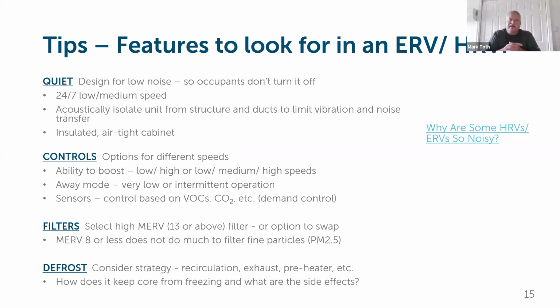On the ERVs, generally, ERVs don't have a defrost cycle that has water, but some do. So it's not a blanket statement. There are some ERVs that need a drain also. The ones that I'm most familiar with do not have a drain. The company I work with mostly has no drain. Units can go in any position at all. There is no defrost cycle because the core does not freeze, even down to minus 25 degrees. So really look into the technology of the unit that you want to purchase to make sure it fits your needs.